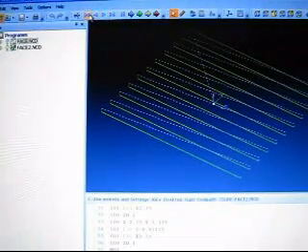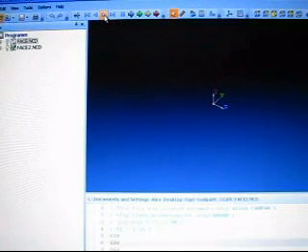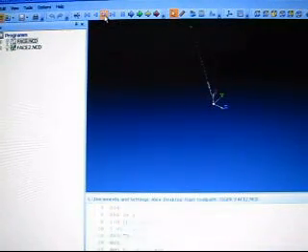What it would do is, obviously, jump off the part to my clearance, and I don't want it to touch my part, so I'll put a piece of paper or something in between there. I just want it to be off the part. Then it's going to plunge, but not into the part. It's going to plunge outside the part. Important to keep that in mind. You don't want to be plunging a big tool into the part. You want that to plunge outside the part.